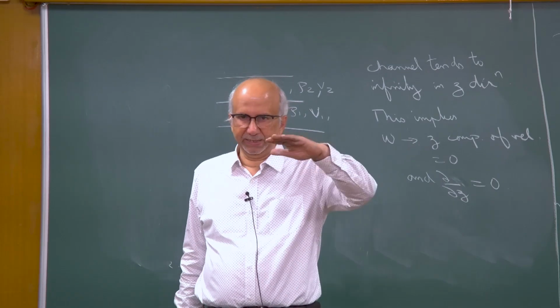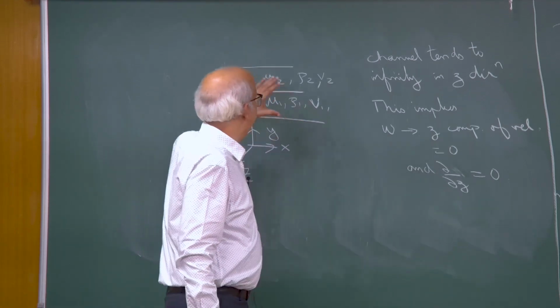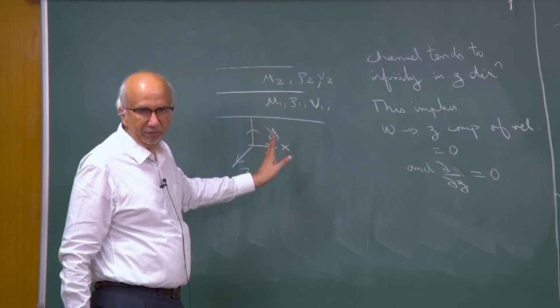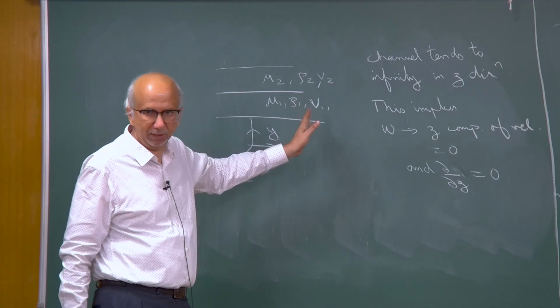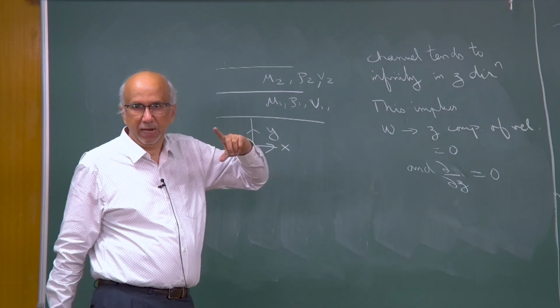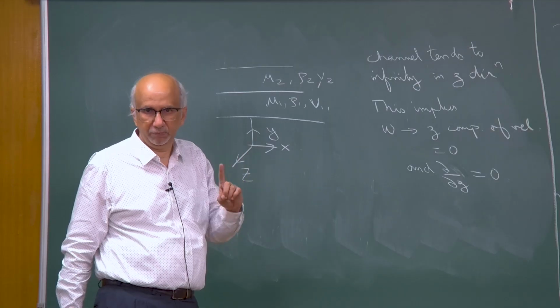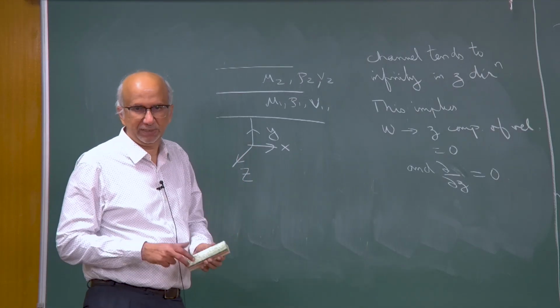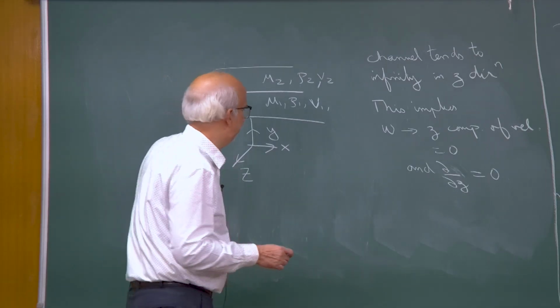So in the z direction things are infinitely long, and our flow is basically going to be in the xy plane. There will be variation in the y direction because it has to satisfy the no slip boundary conditions, okay. And the flow is, this is what I said, we will have only one velocity component varying in one spatial direction. So basically I am giving you the answer right now, but we will see why, how it is coming, okay.